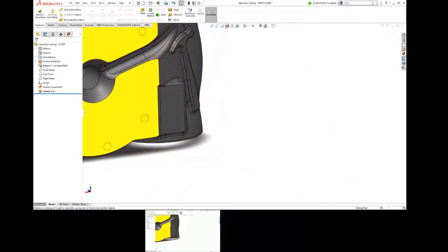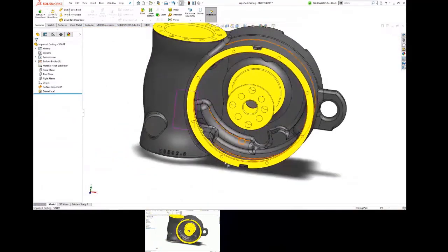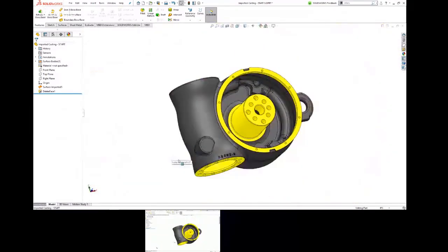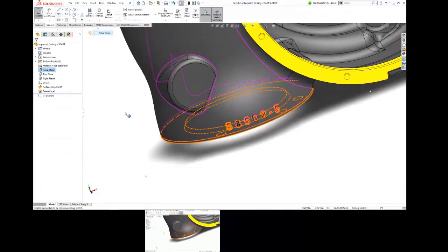This other one, though, gets a little trickier. Again, I think of more of a drywall patch approach. If I were just to sketch a little bit of a volume that completely encompasses that text and just delete those faces away, that could be a pretty elegant solution. So I'm going to try sketching on the front plane.